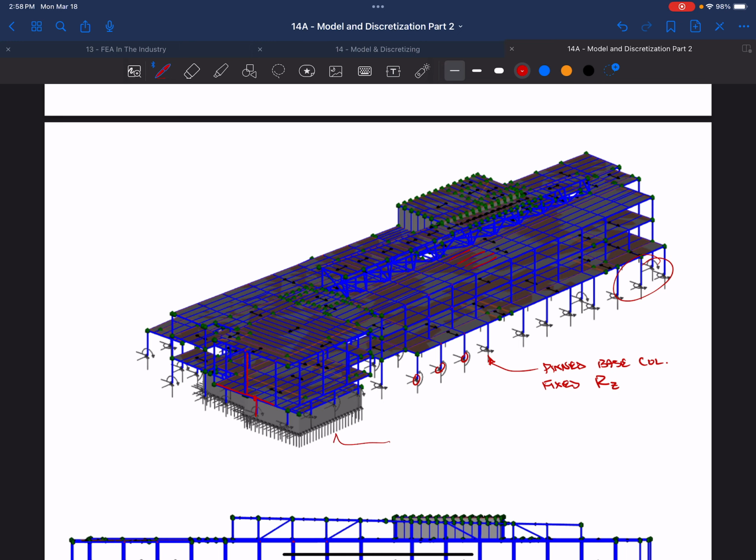So this is a basement for the NaH. And the reason why we modeled the basement is because it actually acted as a diaphragm. It was going to take load out of the moment frames that are framing down from above. That's these big columns here and here, right? And it's going to resist the lateral forces in those columns, pull the load out into the concrete floor diaphragm, and then extend it out into the tops of the concrete walls, right?